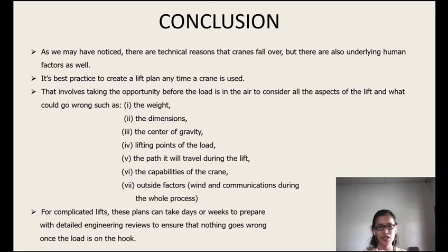It's best practice to create a lift plan anytime a crane is used. That involves taking the opportunity before the load is in the air to consider all the aspects of the lift and what could go wrong, such as the weight, the dimensions, the center of gravity, the lifting point of the load, the path it will travel during the lift, the capabilities of the crane, outside factors such as wind, and communication during the whole process. For complicated lifts, this plan can take days or weeks to prepare with detailed engineering review to ensure that nothing goes wrong once the load is on the hook.